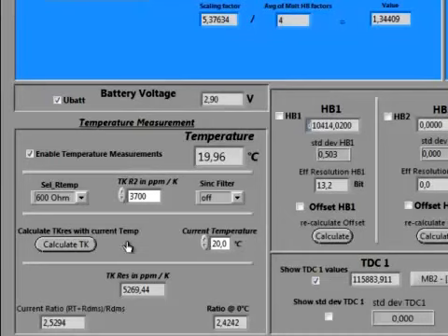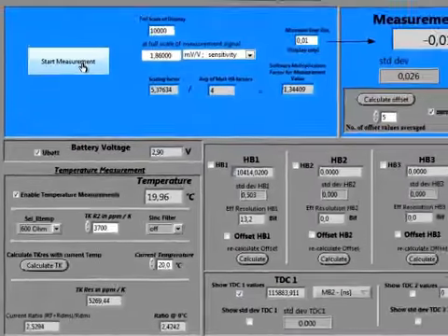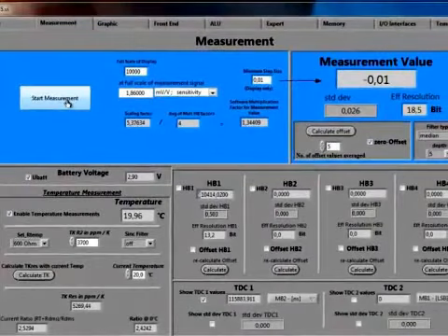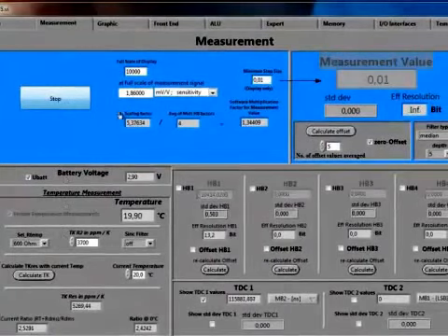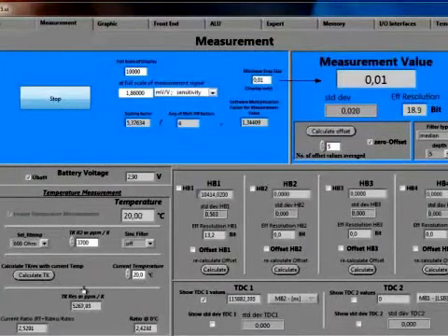The temperature coefficient of resistance TK-res of the combination of the strain gauge resistor and the internal temperature measurement resistor is shown here as TK-res. For a nominal current temperature entered here, this resultant TK-res is calculated once. Once you press the Start Measurement button, all the measurement values in this sheet are updated regularly. Pressing the Calculate TK button will calculate the TK-res here.